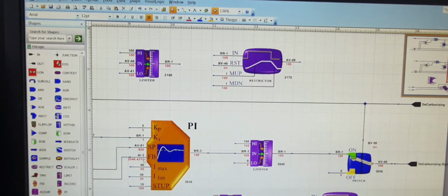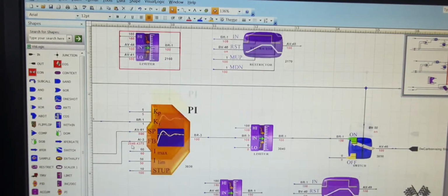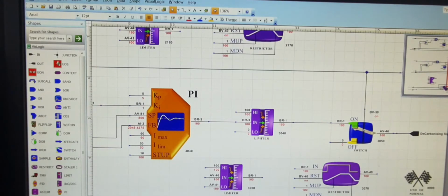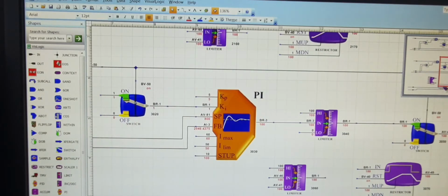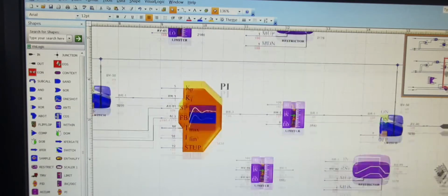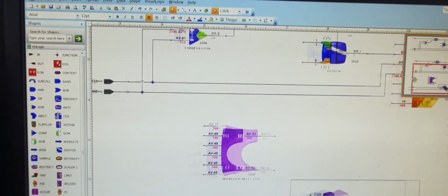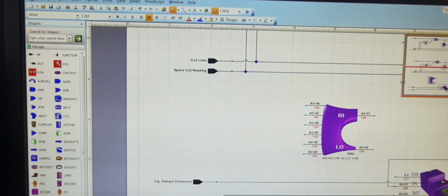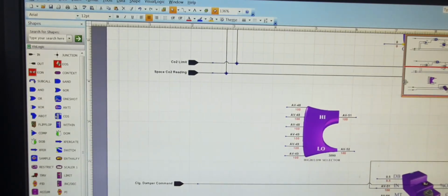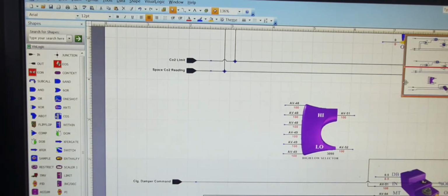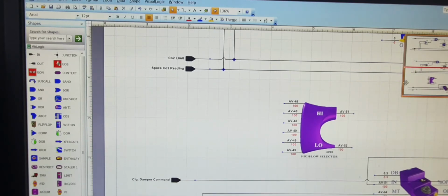And you see this KPKI. So this KPKI is immediately programmed to analyze, with KPKI 1 and 5 as proportional and integral constants. Set point is 800. Current value of the CO2 is 2000. And then we're calling for full ventilation to be energized. So we're opening up everything so as to have fresh air, regardless of what the temperature set points are. We are not caring about the temperature or comfort level at this point. We're giving priority to health and safety.